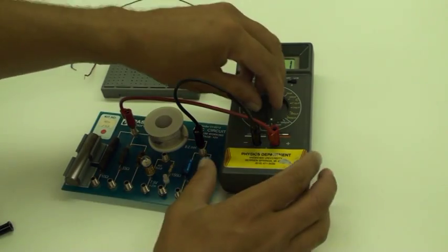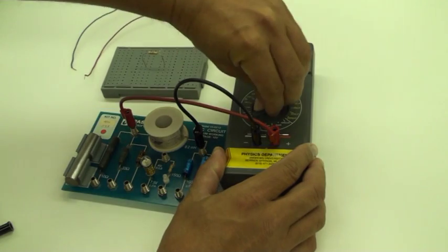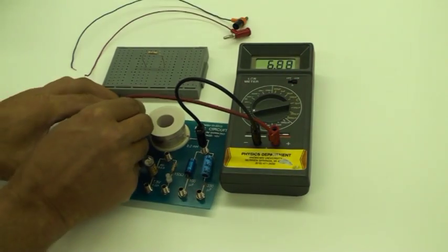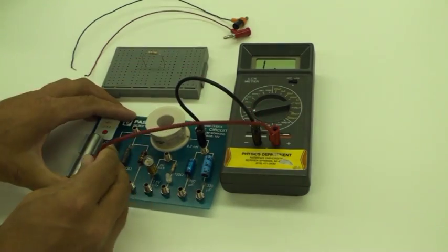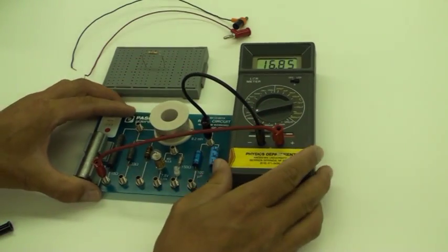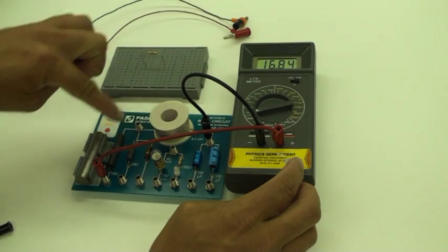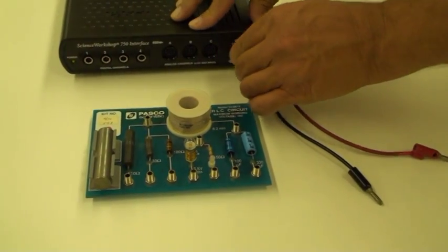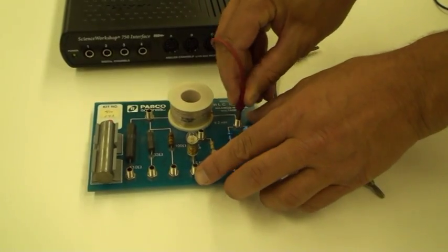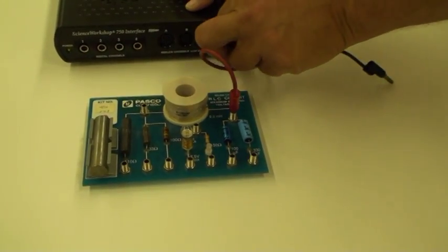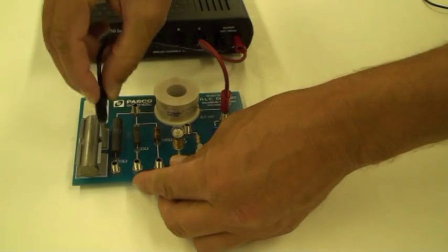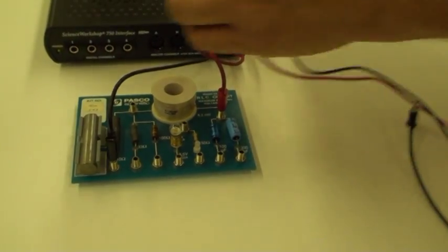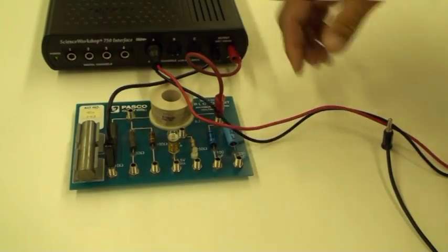Then use the meter as an ohm meter to measure the total resistance of the coil and 10 ohm resistor combination. This is the total resistance in the RL circuit and should be used to calculate the time constant. Because the time constant for this small coil is short, you cannot keep up with a mechanical switch. Use the internal power supply set for square wave mode to flip the circuit on and off.